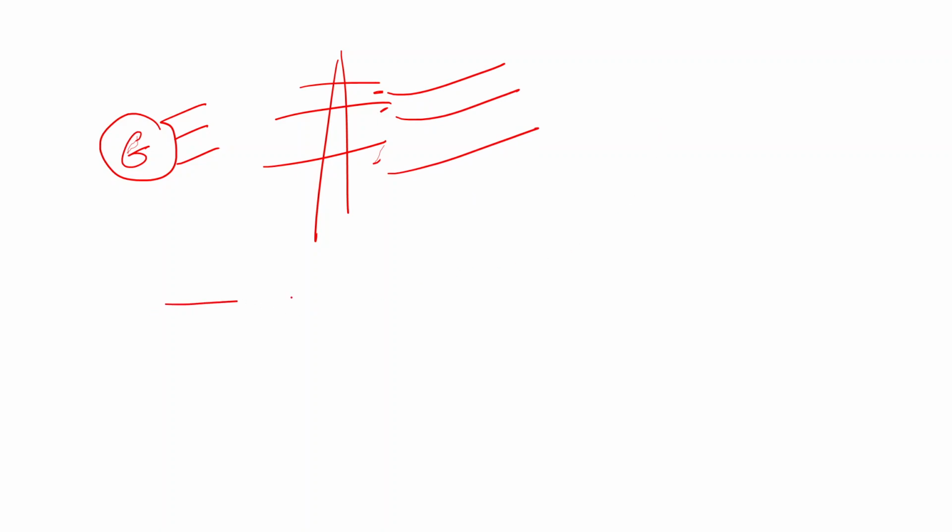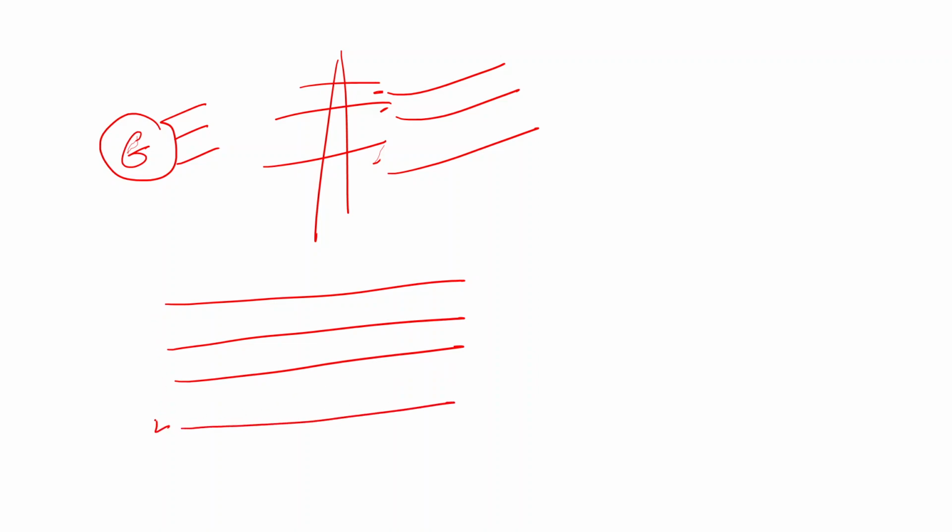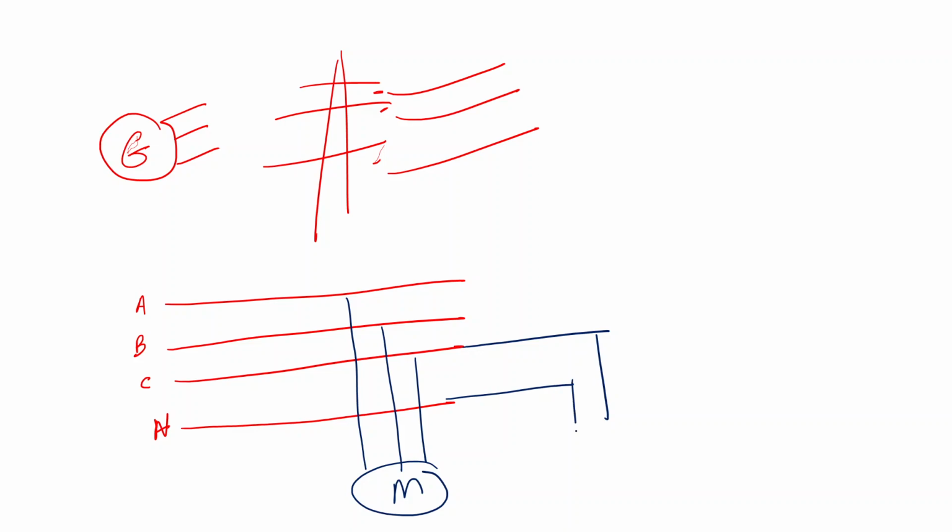And in this three phase, we will have a neutral line when it's close to the user. We have phase A, phase B, phase C. Some equipment will use three phase, like a motor. Some equipment will use only one single phase load, like a lamp, or your household use. So the voltage between phase to phase, or line to line, as we call it, and from line to neutral is a different value, right?